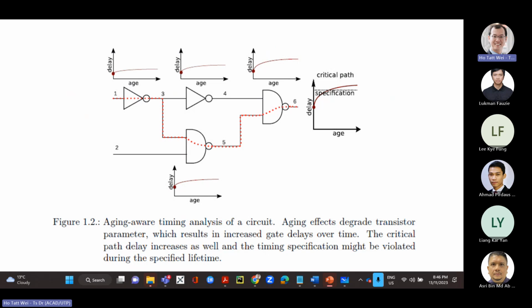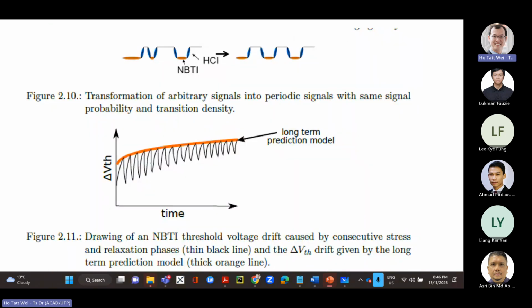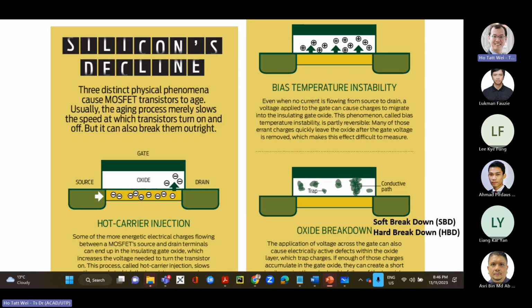So in this case, increasing the VTH will actually reduce the drive current. So you can actually model the increased delay by a change in the VTH. And this delta VTH is a mean value, a change in the mean value of the transistor. So it seems as if you are changing the delay. And we also saw qualitatively, if there are charges trapped in the oxide, it is as if we are reducing the effective VTH. Have we actually reduced the VTH?